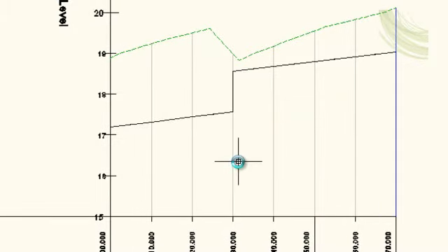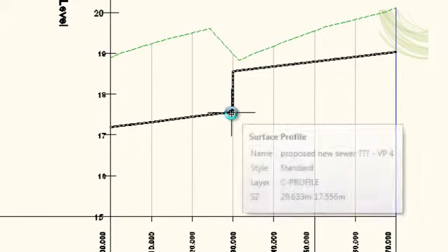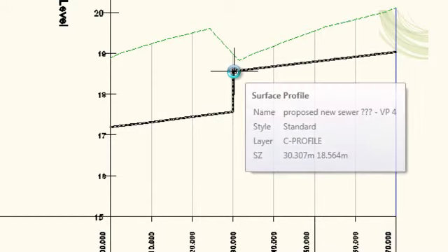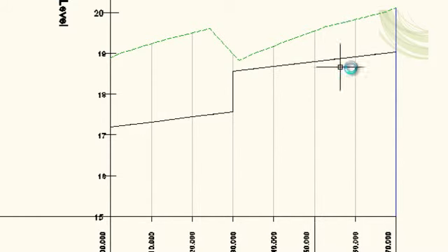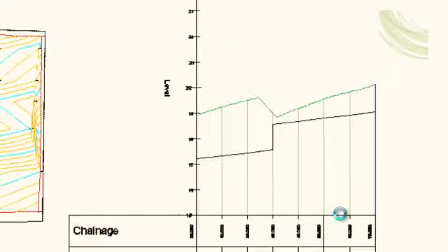And there you can see it has had the exact same effect as previously. We have a chainage of 0, 0 here and a level of 17.2, rising at 1.2% to here, vertical jump here, and then continuing on to the position up above.